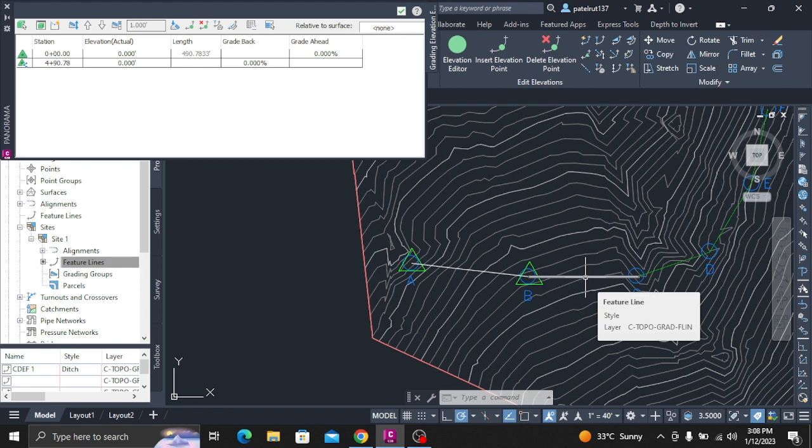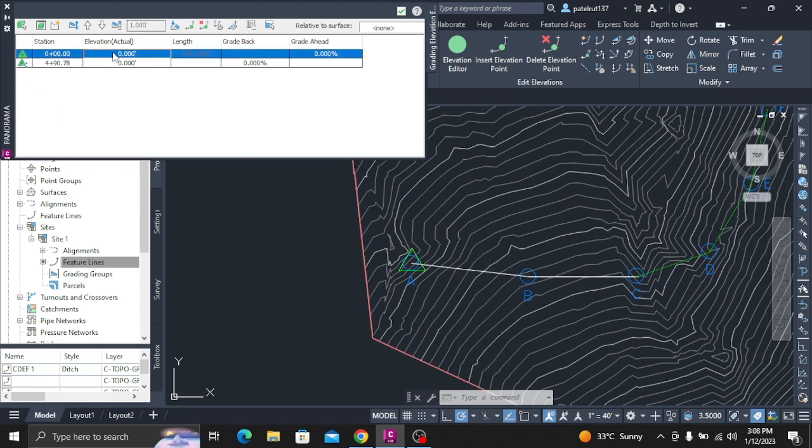Set your display so that feature line AB fills most of the drawing window. Click the Select a Grading Criteria list and click Surface at 4:1 slope. Click Create Grading and click the red target line from the first grading that you created. Enter Yes to apply the grading to the entire length of the line. Press Enter to accept the cut slope, 4:1. Press Enter to accept the fill slope, 4:1. Press Escape to end the command.